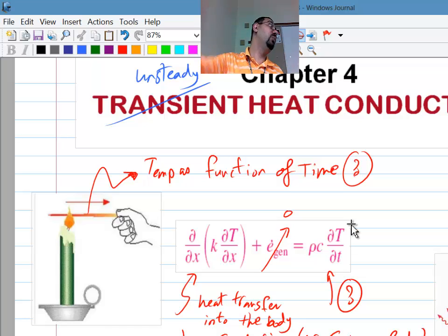Well, then we already did this. That's what we did in chapter 3. You could think about chapter 3, when we were doing the steady state, as if, as Mallory was saying, you just do it for the first second where everything was almost constant, and then do it again after the next second and the third second. During every one of those seconds, the problem would be as if it's steady state. That procedure is called quasi-steady state, where you solve the problem every time step, kind of. We already did this in chapter 3.